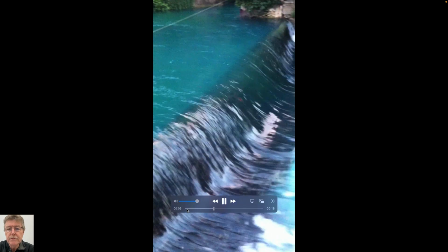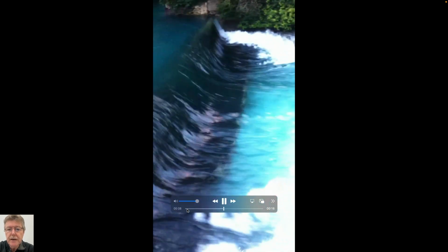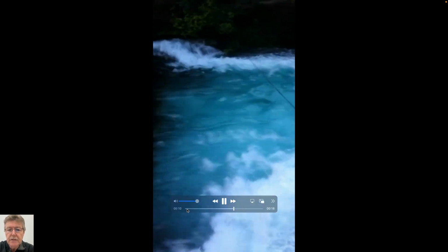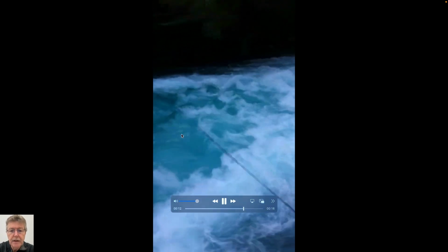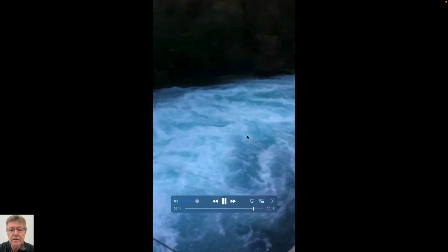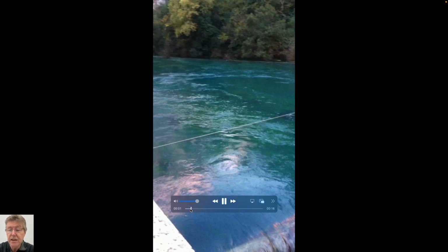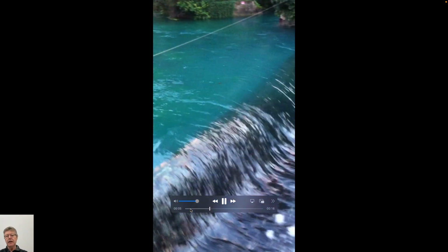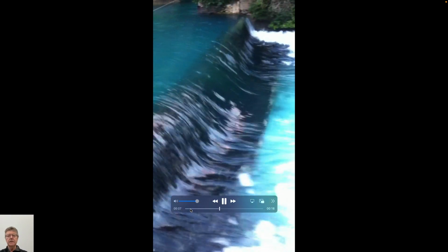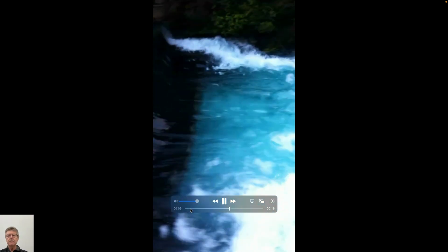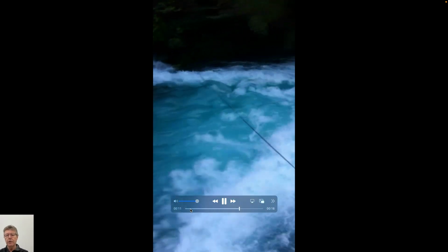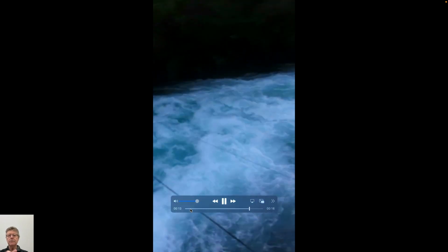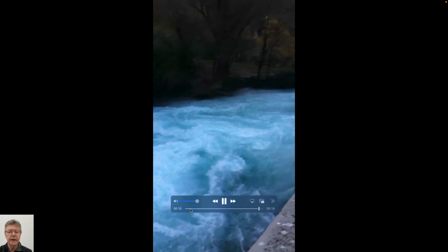Very clear water coming over the lip at some speed, and it's clear and laminar up here, and as it goes downstream it breaks into this turbulent flow. So it's just like the hydraulic jump that you saw before. It's changing its elevation, same volumetric flow rate, but different characteristics of the flow. Shallow and fast upstream, and then slower and deeper downstream.